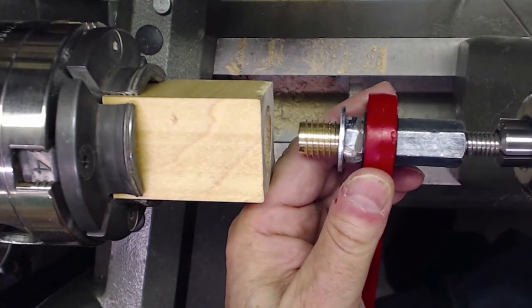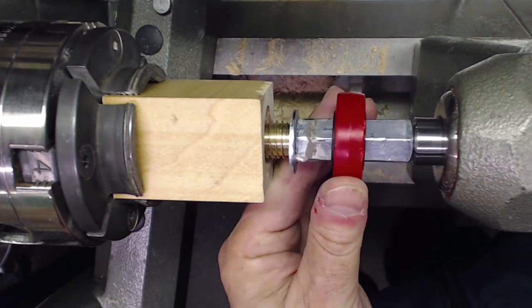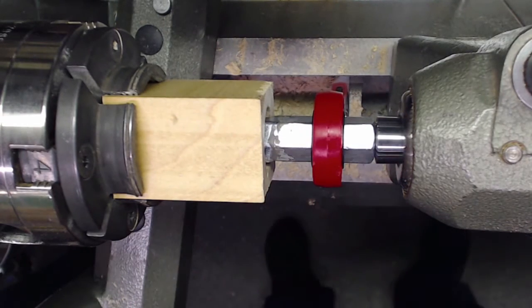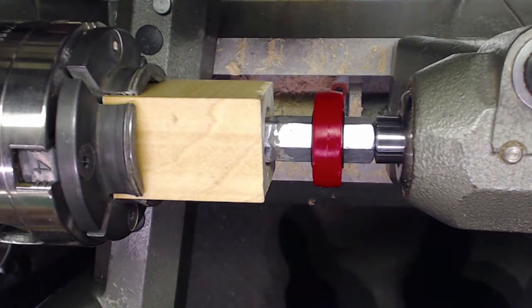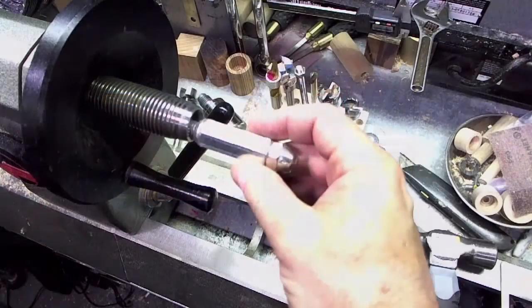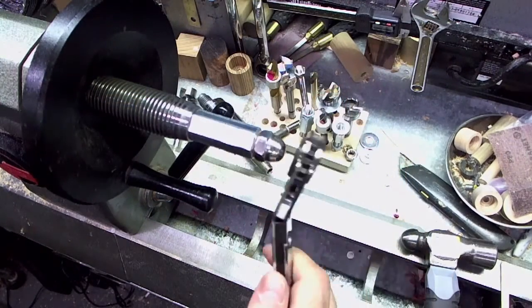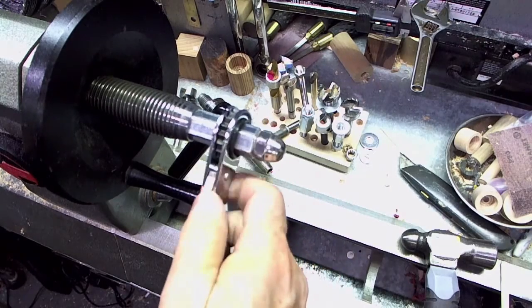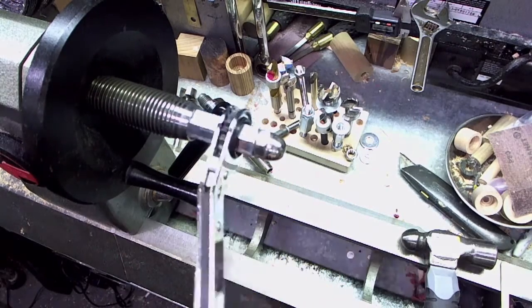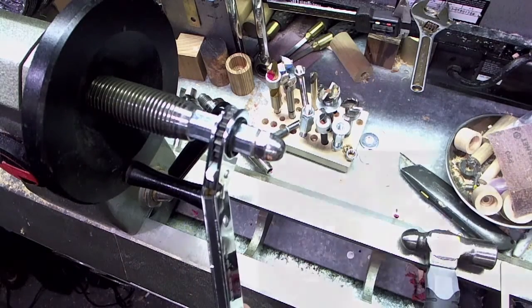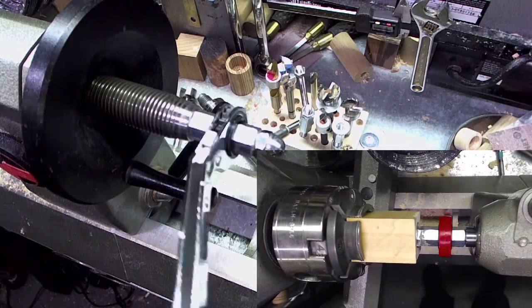And as I mentioned to somebody earlier, the little slots in your threaded inserts are not for you to insert a screwdriver in. They actually go into the wood, and that helps cut the threads. So here I'm using a drawbar and holding a 3/8 inch threaded rod that's going to drive everything in here.